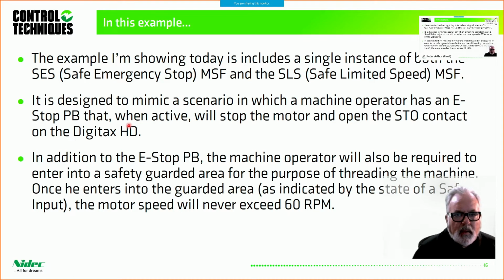Right? Now, in this example, what I'm showing today is a safe emergency stop and safe limited speed. So this setup is designed to mimic a scenario in which a machine operator has an e-stop push button that, when it's active, will stop the motor and open the safe torque off contact on the Digitax HD.